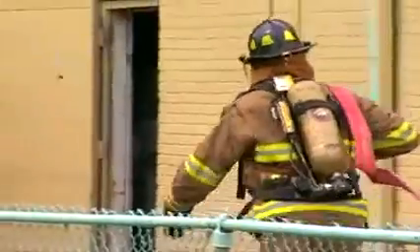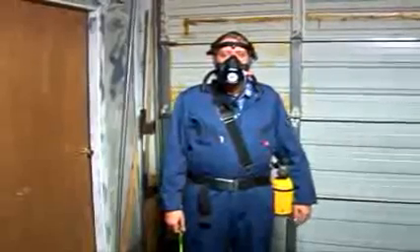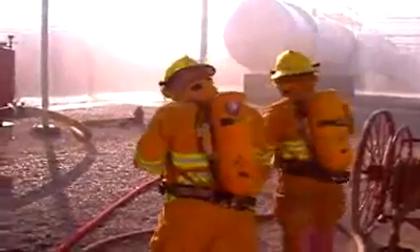An atmosphere supplying respirator supplies clean air directly to the user from a source other than the surrounding air. This type is also known as positive pressure respirators. A supplied air respirator, or SAR, a combination respirator, and self-contained breathing apparatus, or SCBA, are the three different kinds of atmosphere supplying respirators. A SAR makes use of a hose to deliver clean, safe air from a stationary source